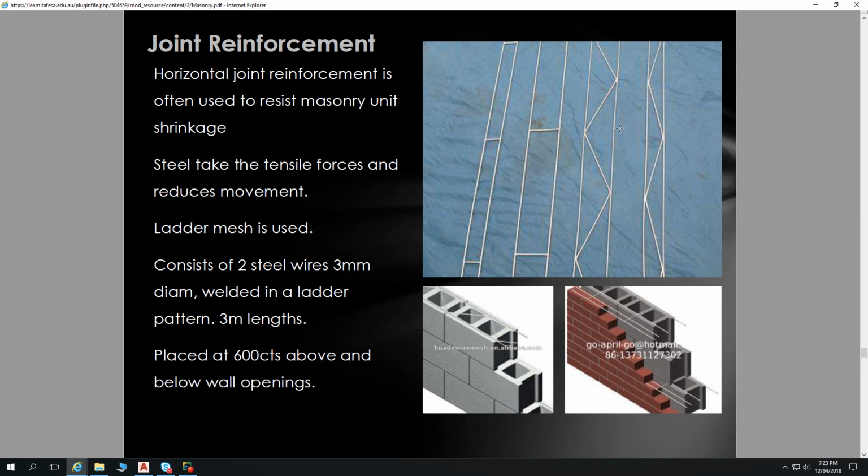Where we have windows, how does that work if there's bricks lower and above? What do you mean? Well, for the height of your window, that's in increments of 86 millimeters. I'll do a quick Google search for the standard window size and see if I can get that on the screen next to our brickwork dimension chart. Brickwork dimensioning works in a horizontal sense and in a vertical sense as well. So have a look at that, and then open up your brickwork coursing chart and see how many of those dimensions you can find within your chart.